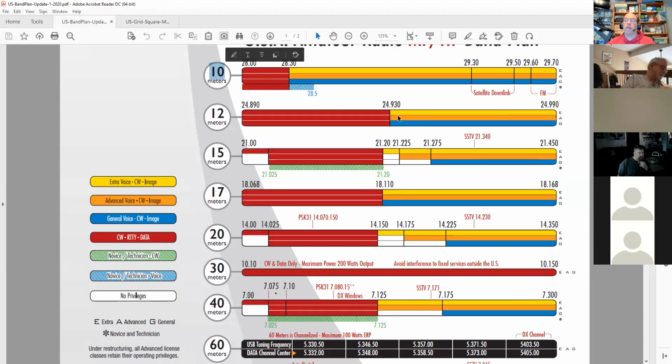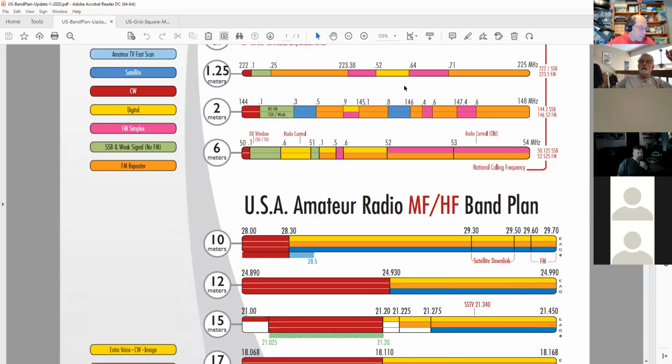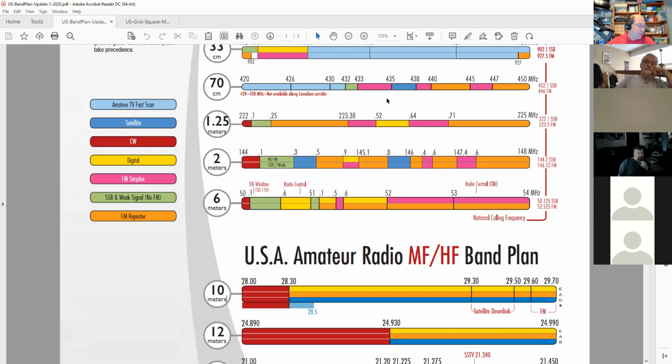10 meters. What's 300 divided by 10, everyone? 30. Clearly 30 is not anywhere between 28 and 29.7. So that is called the approximately 10 meter band. So we call it 10 meters for that reason. Let's see, if we were to say that we're on 146.52 megahertz, which again, what's the name of that frequency? National calling. National simplex calling frequency. You would see that it is on the 2 meter band.